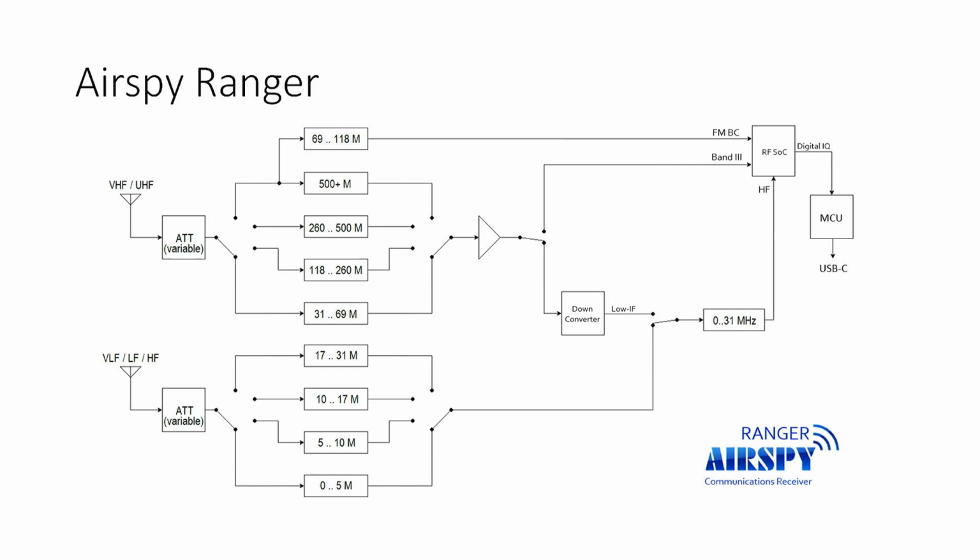This is the latest one from AirSpy, which they've announced, but have not launched yet, because Youssef's having a few manufacturing problems. But I've had a prototype to play with, and it is really good. This one covers from half a kilohertz to 1750 megs continuous. So it's got a very wide range, and when I was playing with it the other week, it's very, very good performance. He's basically taken the HF Plus design and improved it with a whole load of new filtering and a completely new AGC system. So that one's one to look out for in the coming months.